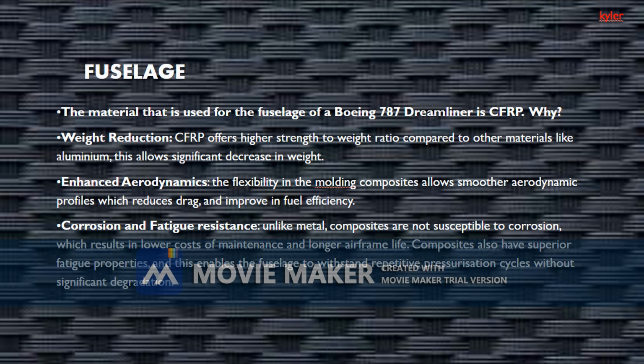CFRP is also flexible and allows smoother aerodynamic profiles that reduce drag and improve fuel efficiency. CFRP is also not susceptible to corrosion, and that lowers the cost of maintenance and lengthens airframe life. Other than that, it has superior fatigue properties, and that allows the fuselage to withstand repetitive pressurization cycles without significant degradation.